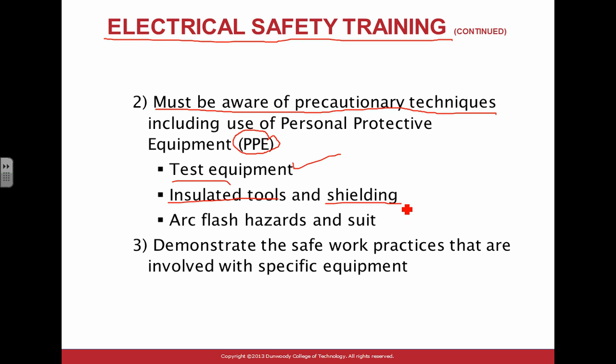Now, I don't know how you guys do it on the 120. Most of the stuff that we do, you guys are coming from a shock hazard, not from an arc flash hazard. Meaning you grab a 120 circuit that's fed from a 20 amp circuit. That circuit will send you to the second life as fast as a 100 amp circuit. Really, for shock hazard, it doesn't matter. If it's 20 amp, from an arc flash hazard, the arc flash will burn you.